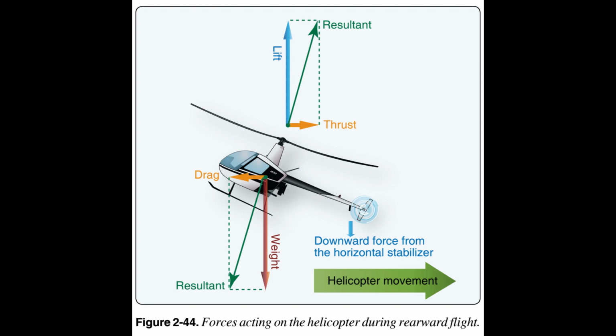Pilots must do a thorough scan of the area before attempting to hover rearward, looking for obstacles and terrain changes. Slower airspeeds can help mitigate risk, as can maintaining a higher than normal hover altitude.